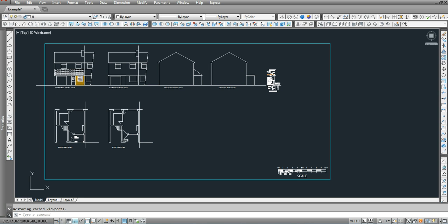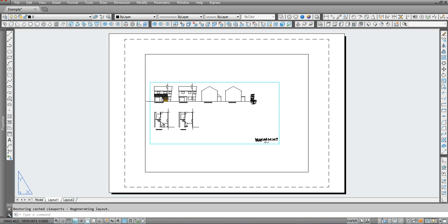So you've done all of this hard work, and if you're like me and you draw 1 to 1, i.e. whatever you're drawing is 1 millimeter to 1 millimeter on your model space, now you want to output it to the layout, which is to be able to print it on whatever printer. Down here you have some tabs. Click on layout 1 and that becomes active.